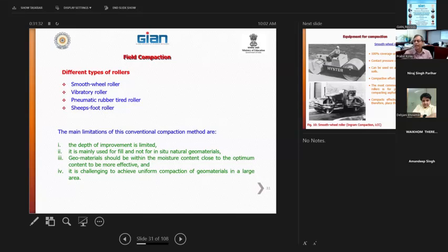Then you have to go to the site and do the field test, right? So, I have one experience with this compaction. I used to work for a Dutch company, where most of the time the compaction was done in the evening, on the whole night. The problem was, instead of layer wise, they put a thick layer of clay and then just rolled it.